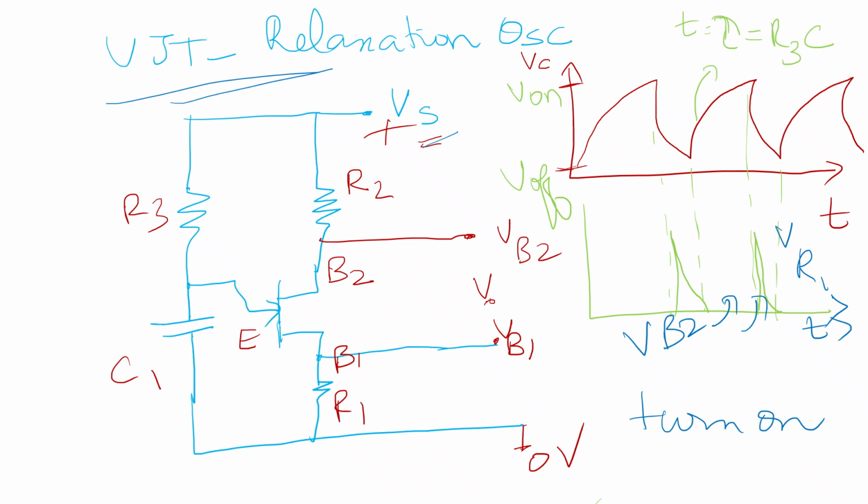So in today's video, we have discussed LC oscillators. There are two types of LC oscillators, the Hartley oscillator and the Colpitts oscillator. In the Hartley oscillator, the tank circuit, that is, the capacitor and the inductors, are connected in the feedback path in parallel. The two inductors are connected in such a way that their center tap is grounded. In the Colpitts oscillator, in the same manner, the capacitor and inductors are connected in parallel with the feedback circuit, but two capacitors and one inductor are used. These two capacitors are connected with their center tapping grounded, in parallel with a single inductor.